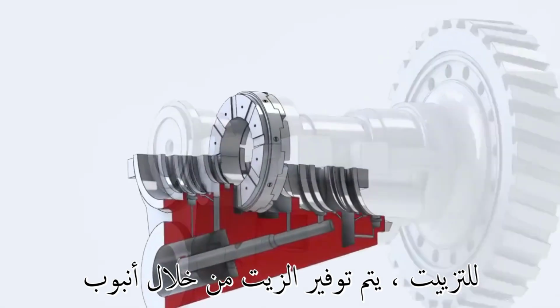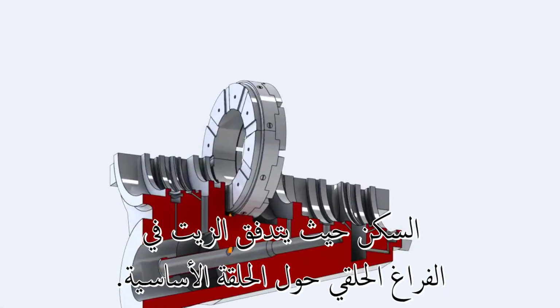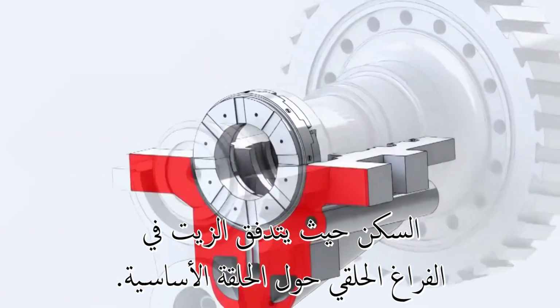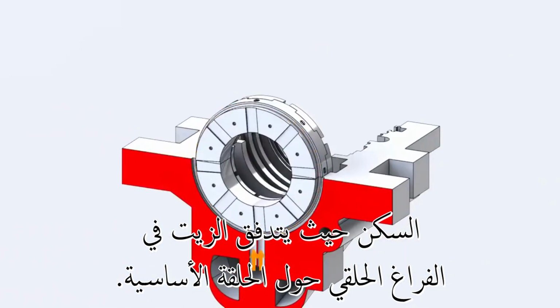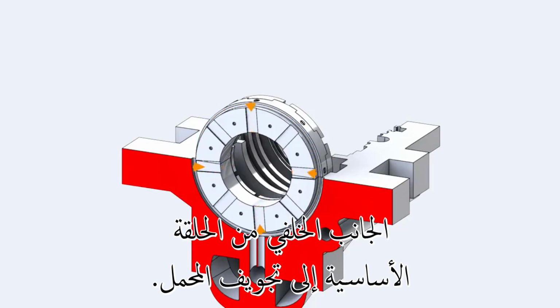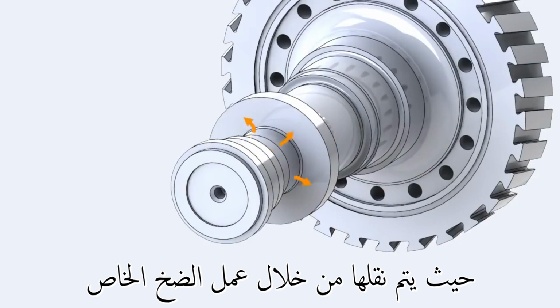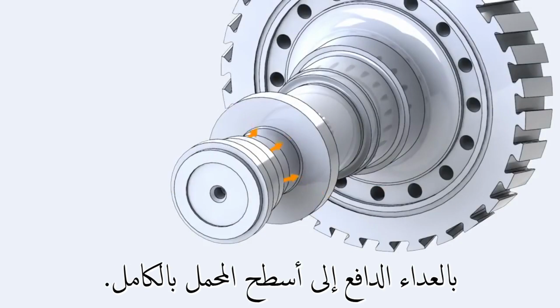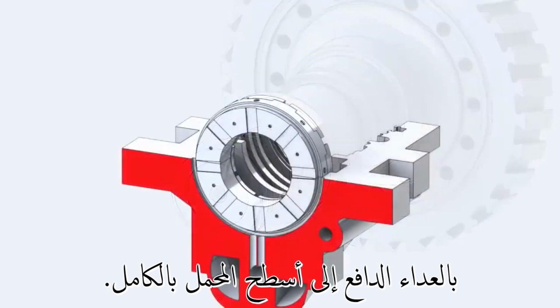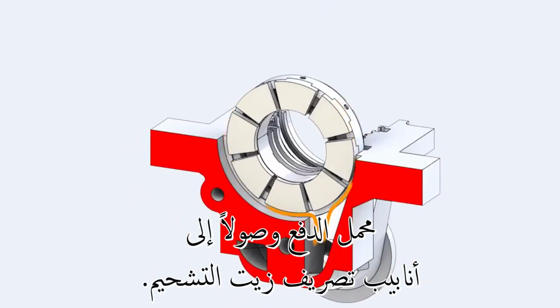For lubrication, oil is supplied through the oil feed pipe to two ports in the lower bearing housing, where the oil flows into annular space around the base ring. Then, oil flows through grooves machined on the backside of the base ring to the bearing cavity, where it is carried by the pumping action of the thrust runner to the entire bearing surfaces. Oil exits at the pad's periphery to the thrust bearing drain cavity down to the lube oil drain piping.